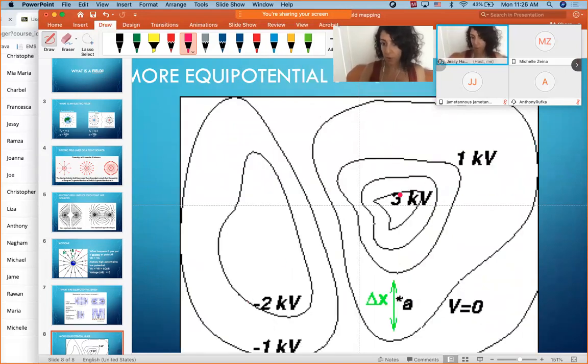Also, this would show you some equipotential lines. So you can call this the equipotential line that represents 3 kilovolts, a constant potential. This is another constant potential, 1 kilovolt. The 1 kilovolt per se means nothing. It's 1000 volts with respect to a reference. The reference is here. It's where the potential is equal to 0. And you see different shapes and different curvature depending on what source you have.